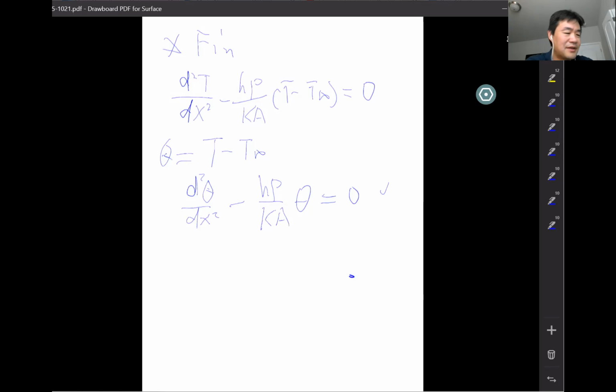Any questions here? Do you know those letters? Look at the drawing I sent you. A is the cross-sectional area. What is P? P is the perimeter. H is the convection heat transfer coefficient. K is the thermal conductivity. Something not in the equation is the length L, and Z is the other dimension. And the thickness of the thing you use the letter T. We will see it later; you will probably need to apply T for something.